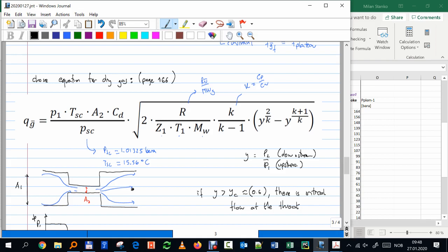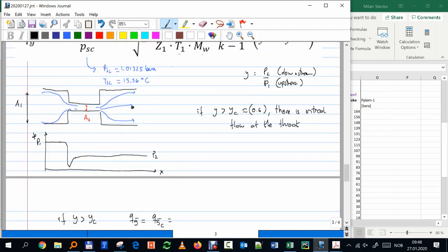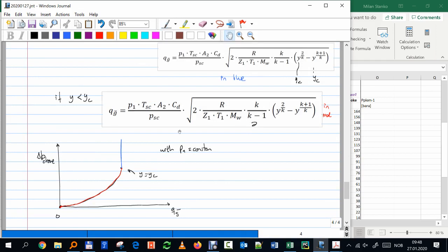We are not going to talk too much about choke. We don't care about choke. We can actually do our calculations without looking at the choke equation. But I just want you to be aware that when you go to commercial software, they have these equations programmed inside, and all the choke models that people have proposed. So that's the complexity. You include that equation, which is actually in two parts, because that behavior cannot continue forever. You cannot increase the rate as much as you want. At some point you reach critical flow in the throat, and then you're done. You cannot go higher than that rate, no matter what delta P you put across.